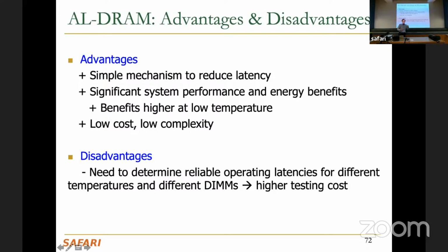Now, again, the ideas that we discussed earlier can apply, meaning, do you need to do this testing offline or online? Actually, I believe that online testing is a lot better. Over time, you figure out. I think online testing is in general much, much better than offline testing, because if you do offline testing, you have to guarantee the timing parameters are correct after you ship them, because you're not going to do any online testing, right? So that requires a lot of cost.